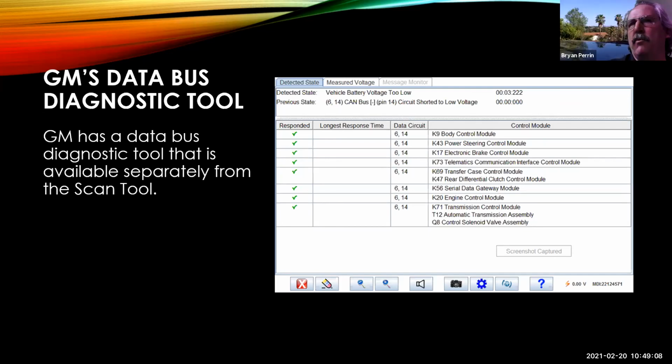With the gateway, where you're going through a gateway and it's not catching up as quick, or it's expiring on the timer on the scan tool. I have had that, where at first I'm getting no communication, refresh, and now all of a sudden someone's talking. Now everything works, and there's nothing wrong. I've just not had it with one module, but I have had it with everything. Yes, that's what I mean.